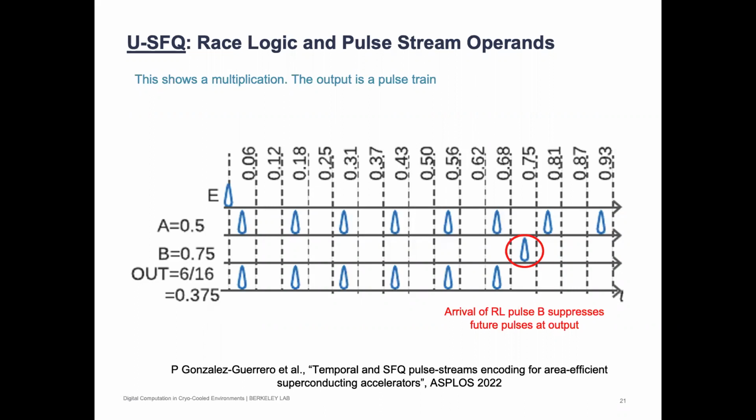They could be derivative of that epoch. So it can be a comparison, but you have to remember, we can do a lot of arithmetic without that. Like the first arrival, they don't need the pulse at every time slot. They just take two inputs and they produce an output. So we only do this, if I can call it synchronization, at boundaries, but not at every gate. It's kind of like wave pipelining, if you're familiar with the term from CMOS, where the computation propagates as a wave, kind of asynchronously, but made to be in sync with each other, without a clock. And then it gets synchronized at boundaries every so often.